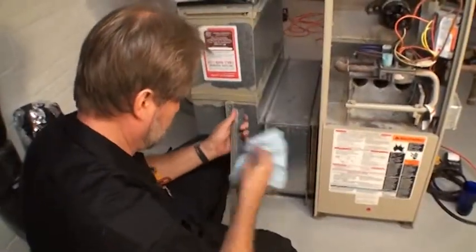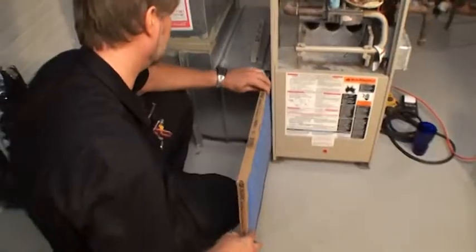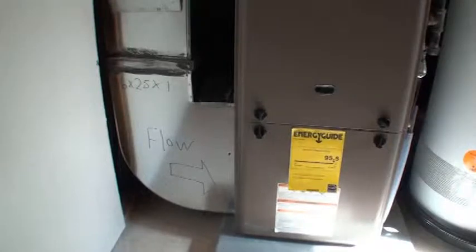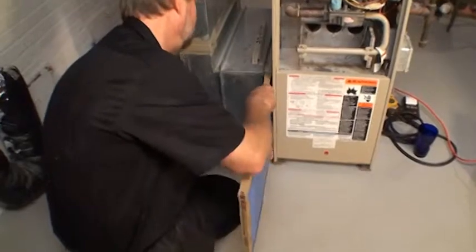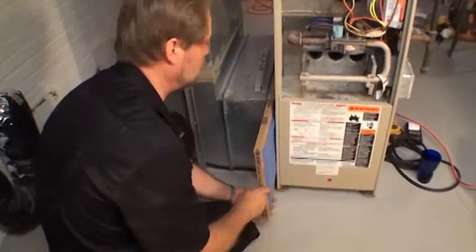Install a new furnace filter for every furnace that you clean and tune. Educate the client on the importance of changing or cleaning the furnace filter monthly. The furnace filter size and airflow arrow needs to be written on the return drop in permanent marker. For furnaces with electronic air cleaners, you will need to explain the importance of cleaning the main filter every 90 days and the pre-filter every 30 days.